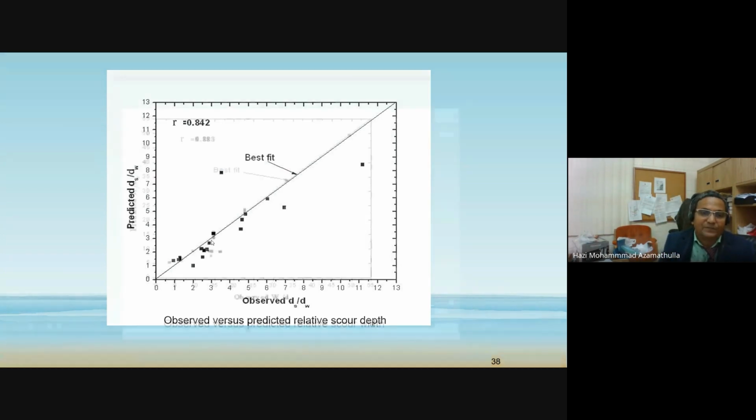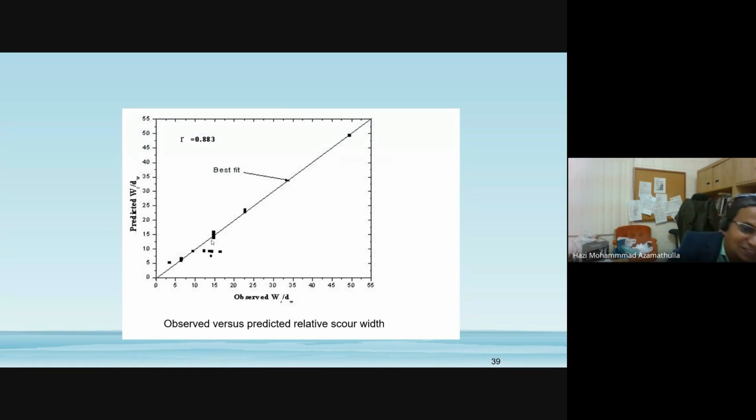Next please. In case of scour depth, and then in case of scour width also. Agreed. But in case of scour width, it is all under predicted. I showed you some negative values coming, and lateral energy dissipation is very difficult since my flow and my hit are going directly, not laterally, not to the side. Next. In case of location, it's working very well.